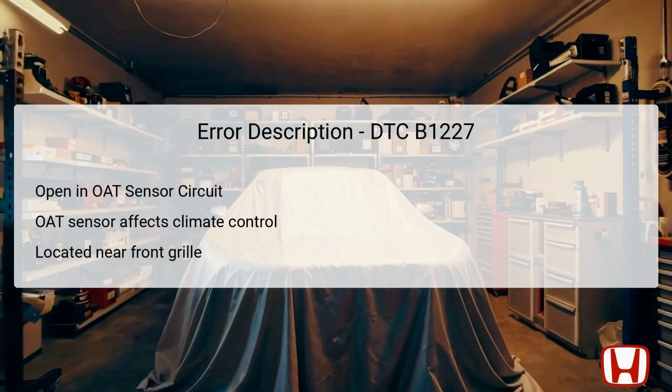B1227. The DTC B1227 indicates that there is an open circuit in the outside air temperature sensor, which can cause the climate control system to function improperly. The OAT sensor plays a crucial role by supplying real-time temperature data to the climate control unit, allowing it to make necessary adjustments to heating and air conditioning. Situated typically at the front grille, this sensor is exposed to outside atmospheric conditions, and its accurate operation is essential for optimal climate management inside the vehicle.